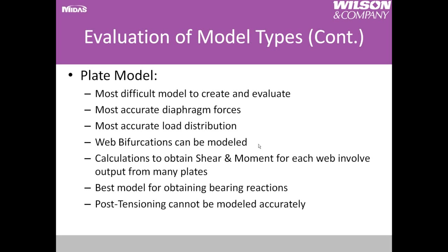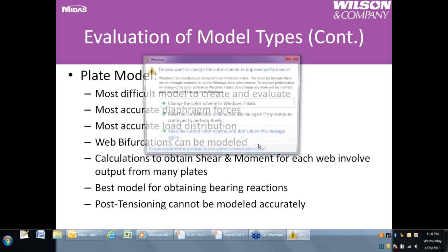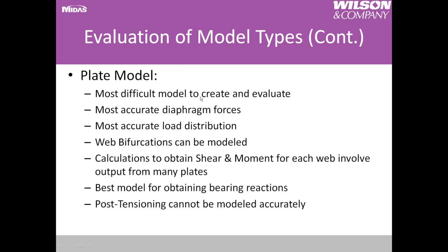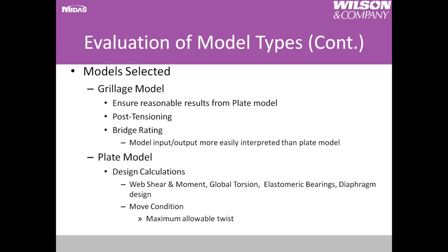Taking a look at the plate model, this is the most difficult model to create and evaluate. It's the most accurate in terms of the diaphragm forces, in terms of the load distribution, and for the bearing reactions. Kind of the negatives of the plate model were that the calculations to obtain shear and moment for each web involved the output from many plates and required a fair amount of work to obtain those. And the post-tensioning could not be modeled accurately.